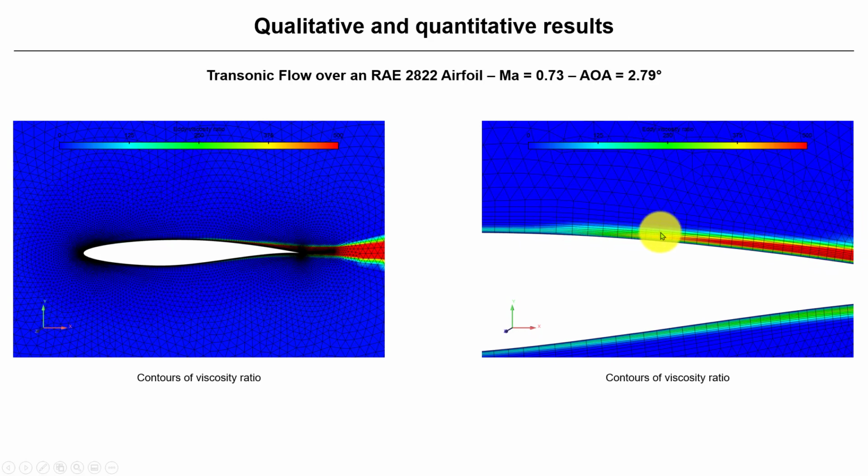Remember that we talked about the viscosity peaking in the middle of the boundary layer, you have it here. Probably you see that if you look at the airfoil in most of its extension, this mesh is okay, except here close to the trailing edge. Maybe it would be a good idea to add another transition layer or reduce the transition. But it's not that critical, it's not that bad. But this is what I was talking about. See here that you start to see that you are adding some diffusion there, that in some situations might be critical.